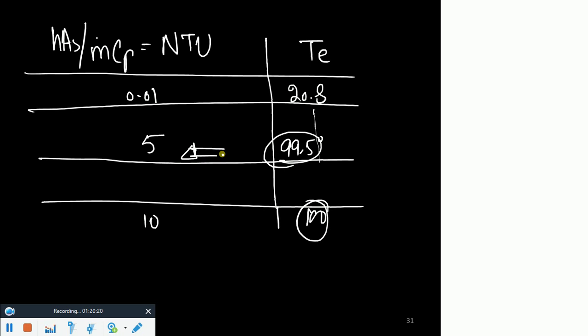But if you even try to increase the pipe length, now my point is, if you increase the pipe length, why? Because if you increase NTU, you increase the pipe length, isn't it? NTU is what? Perimeter into L, right? So h perimeter L over m dot Cp. If you increase the pipe length to enhance the surface heat transfer, there would be no benefit of that increase in length beyond a certain point. You would just be wasting your resources, right? So you need to make sure that if you are designing a pipe, you should keep NTU around 5.